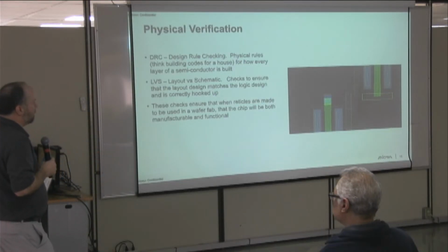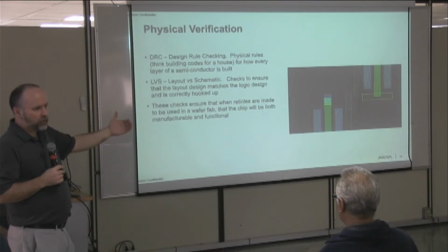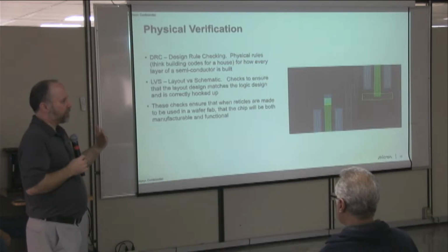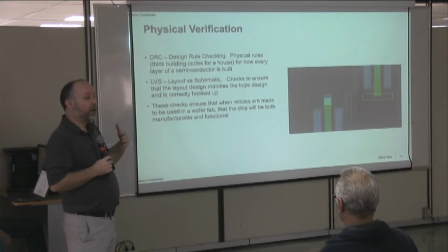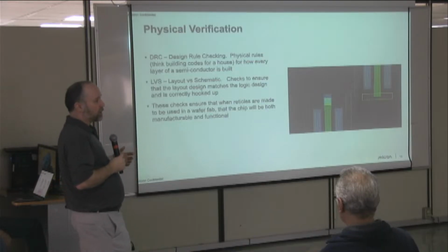Similar with LVS, that's a very critical thing for us, where we have to check and make sure: do we have the right number of devices? Do we have the right kind of devices? And are they all hooked up correctly?